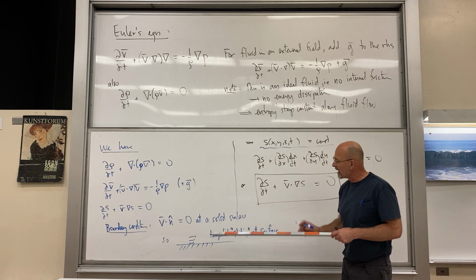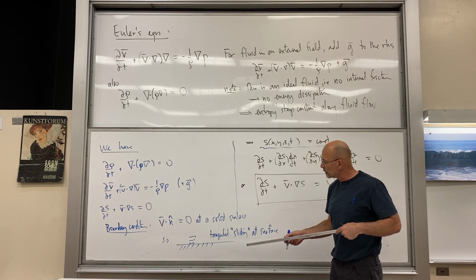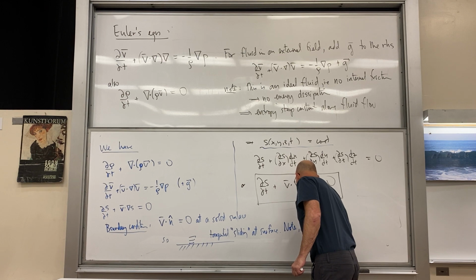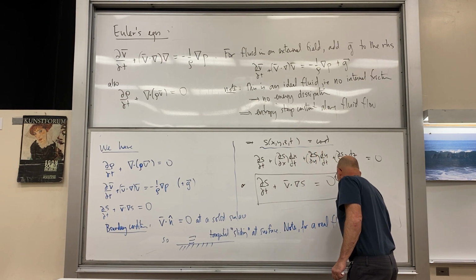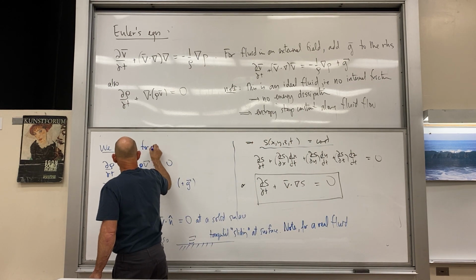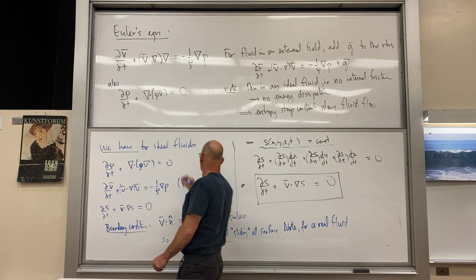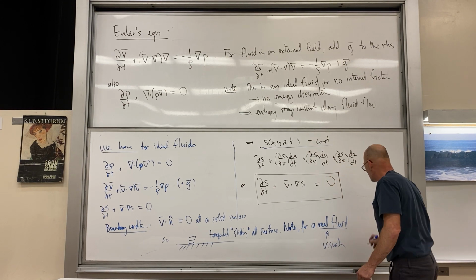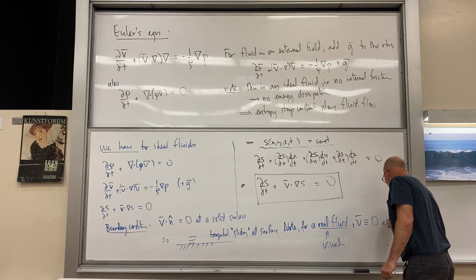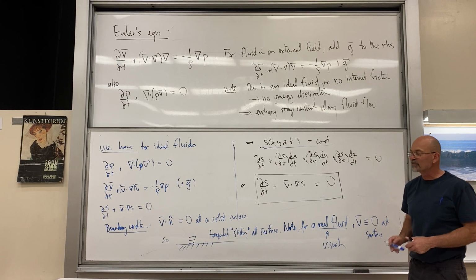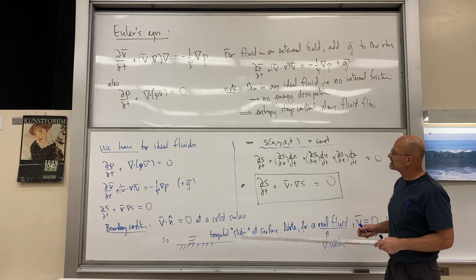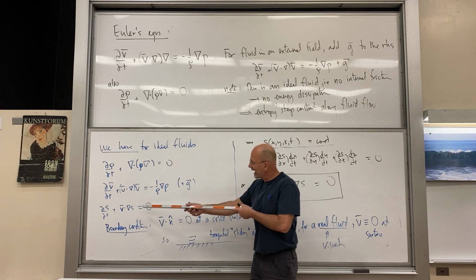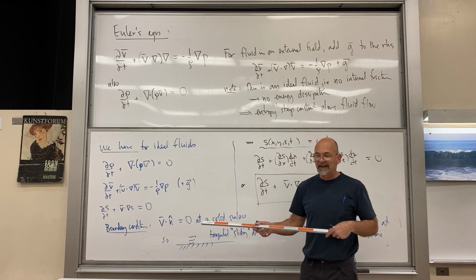This is the big difference in boundary conditions between these ideal fluids and a real fluid in which v completely vanishes at a surface. So note, let's write ideal up here for ideal fluids. For a real fluid, and that means it has viscosity, v is identically equal to 0 at a surface. Okay, so that's the difference between the two. So that's a decent derivation of all these things. It's thermodynamics that will link entropy, pressure, and density, but typically we don't need that much.